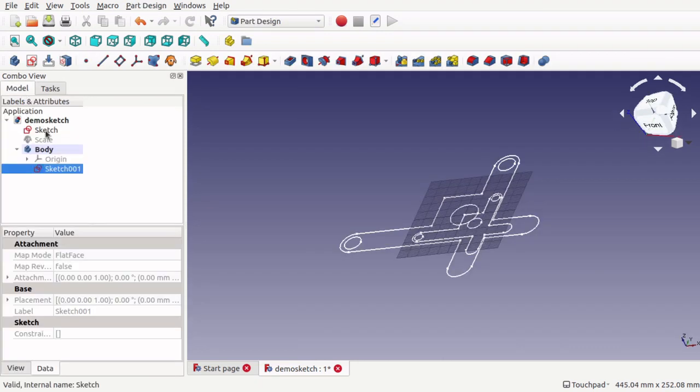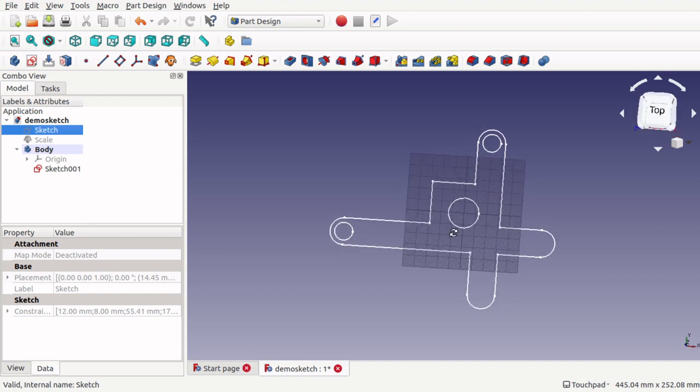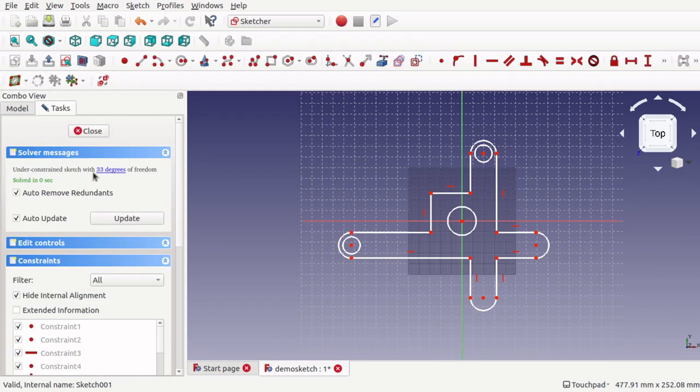If you do want to pull through all the constraints, you would have to go about this a different way, and that's using a spreadsheet to scale this. What a spreadsheet does is that you can take each of the lines of the sketch, create an entry in your spreadsheet for the width or the height or the length or the constraint you place on there, attach those by a formula to these lines, and then use the spreadsheet and just take the cells and times them by the factor that you want to scale it to.